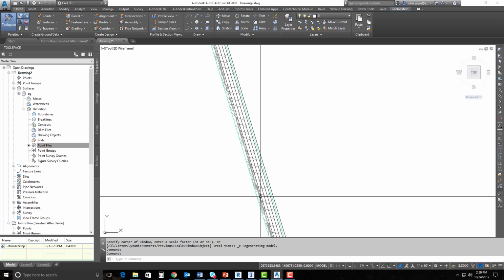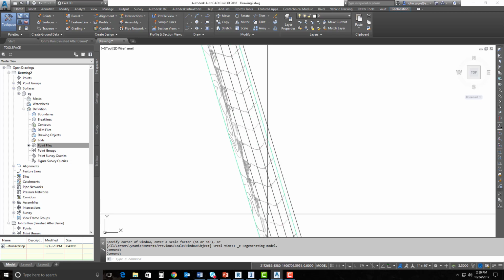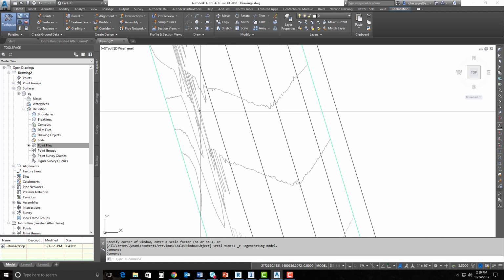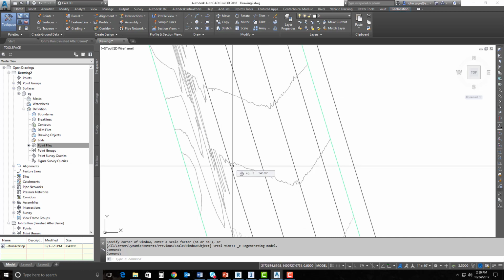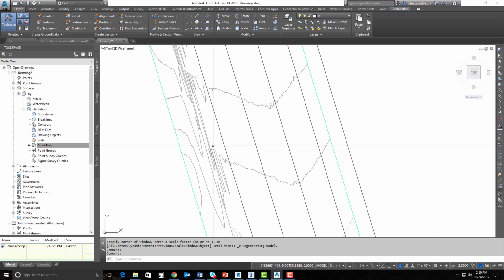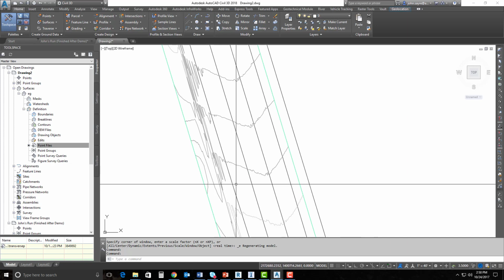So once this surface is generated, I can see my contours. You can see just a little bit of interference here that was in the point cloud itself. And we can get rid of that interference a little bit if we go back and reset our transverse lines, how it was sampling along those lines, from a half a foot to maybe a foot or 3 feet. It's just an iteration process on this particular point cloud, but it will take that interference out. That still looks very, very nice.